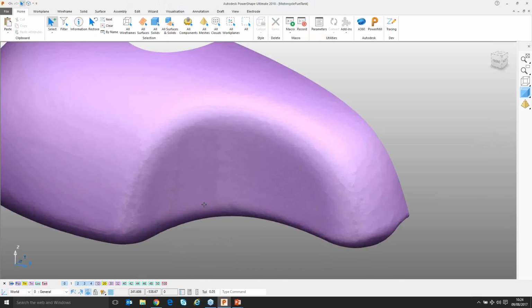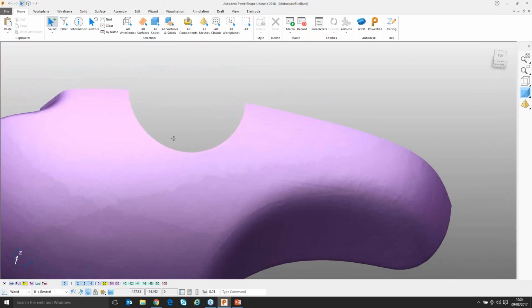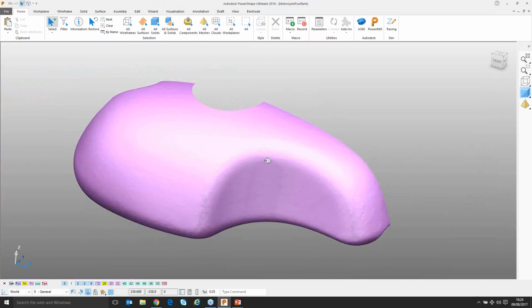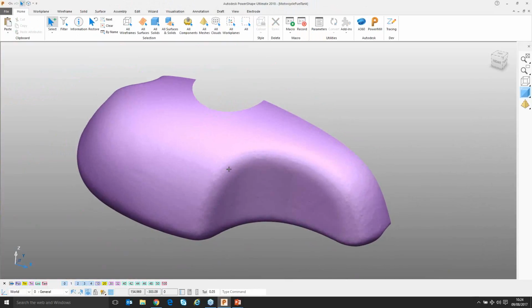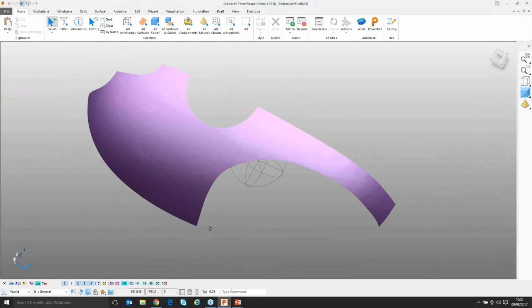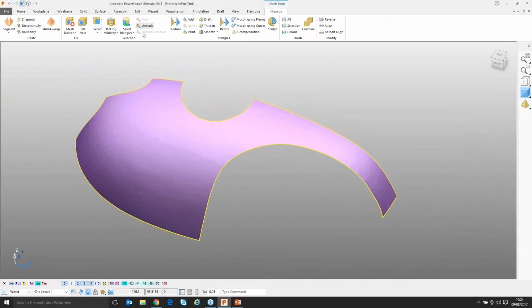Because what we can do is, using the techniques that you saw earlier where I limited this region here and limited, what else did I limit? Oh, I limited the halfway marker on the triangle set. I could draw in some wireframe for the regions that I want to surface as those large blankets. And what I can then have are effectively triangles that represent the entire model, but broken into segments. So you can see here, I'll just draw one of them. That's that initial segment where I've limited out using the limit command on the edit toolbar and some wireframe, the region that I'd like to surface.